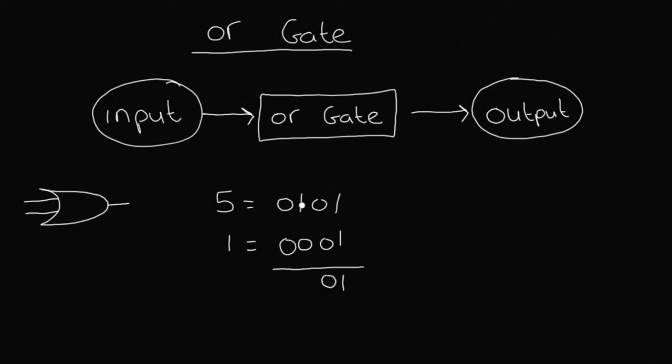And then when we look at the third column, we can see we've got 1, 0. So again, once we've got a 1, we can bring it down because this is an OR gate. Now if it's an AND gate, it would be a little bit different. And again here we can see 2 zeros. So 2 zeros would give us an output of 0. And if you actually look at this number here, you'll see that this number here is equal to 5.